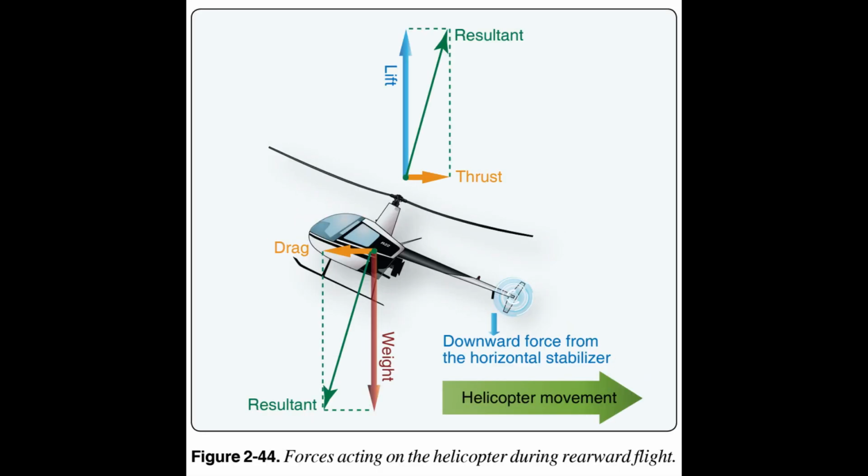Contacting the ground with the skids during sideward flight will most likely result in a dynamic rollover event before the pilot has a chance to react. Extreme caution should be used when maneuvering the helicopter sideways to avoid such hazards from happening. Refer to Chapter 11, Helicopter Hazards and Emergencies.